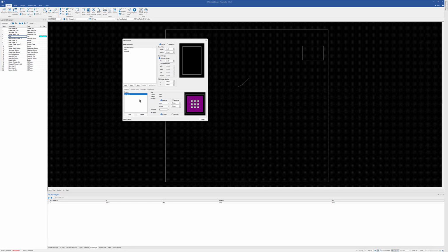And let's go ahead and add our fiducial. Again, we'll use the relative mode. I just find that easier. Absolute's based off the datum point down there. Let's put this in the center of the top, just like most fiducials are. And we'll put it 0 in X, but we'll bring it down to 0.5 in Y. So there's where it's going to go.